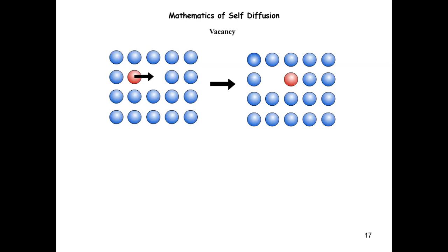Okay, so the diffusion of the actual material atom and the vacancy, which I didn't show, are complementary to one another, and it's actually the same process, right? We can say this atom is diffusing, or we can say this vacancy is diffusing around in the system. These are two different ways of looking at the same process. But the key point I want to introduce here is that vacancy is crucial for self-diffusion or substitutional diffusion, okay? And we will see that there's a physical consequence for how this comes into the picture of diffusivity. So for the sake of time, I'll just stop here. Let me stop recording.